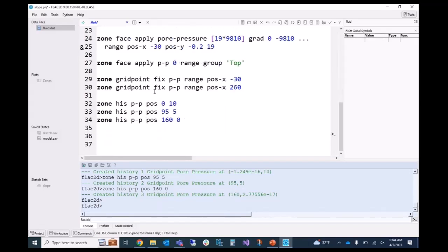Okay, and one property I forgot to set, which is you need to specify the fluid bulk modulus. In this particular case, we're just trying to get to a steady state solution, sort of infinite time. So the fluid bulk modulus doesn't really matter that much. The fluid bulk modulus is important when time is important. In the case where time is not important, we can set it to be almost anything. Hopefully you talked about that yesterday in the fluid class. There is a minimum. You don't want to set it to be some stupidly small number. This doesn't work. So you can kind of work out what that minimum number is, but it's not super important.